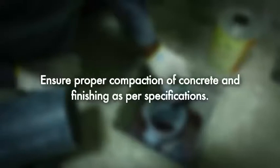Do's during precast production. Ensure proper concrete cover to the reinforcement. Ensure all the inserts are properly placed to prevent any dislocations. Ensure proper compaction of concrete and finishing as per specifications.